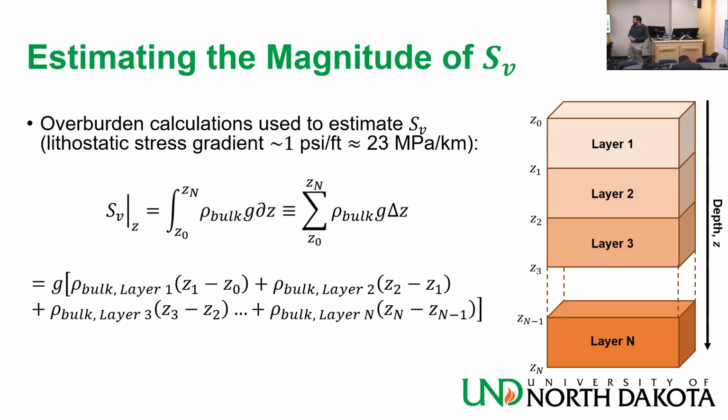If you are using American units or oil field units, then your density is pound mass per cubic feet, and your Z is in feet. How do you go from pound mass to pound force? What is equal to mass times acceleration? Yes, but in American units, you don't need to do that. You don't need to multiply by G. Why? Because 1 pound mass in standard conditions exerts 1 pound force.